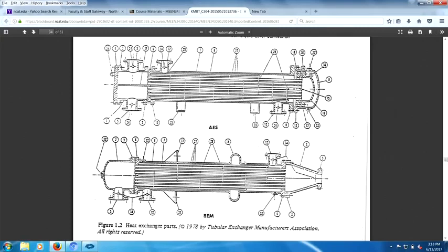The fourth hold point might be to watch how they handle this expansion joint. You want to be there when they pressure test a bellows. You should recognize that what we're talking about has implications through all kinds of equipment.